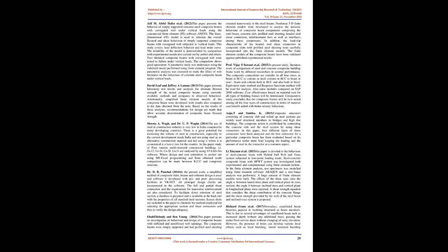All principal design checks are incorporated in the software. The full and partial shear connection and the requirement for transverse reinforcement are also considered. To facilitate direct selection of steel section, a database is prepared and is available at the back end with the properties of all standard steel sections.